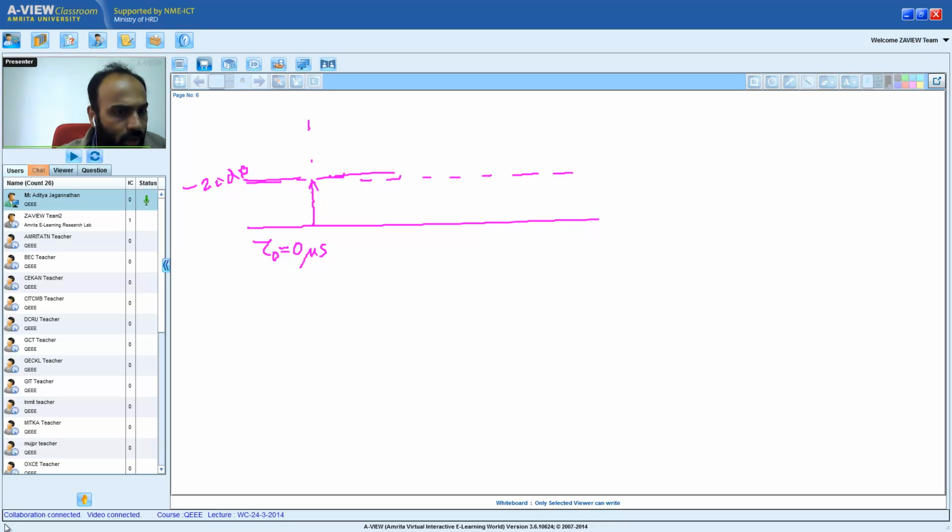Scattered paths, diffracted paths, they are exactly the non-line of sight paths. Non-line of sight means basically scattered and diffracted paths, because these are precisely the non-line of sight components, the scatterers and diffractors in the path of the signal. Because there are a finite number of such objects, the number of non-line of sight components is also finite in practical scenarios. I hope that clarifies. Is that okay?